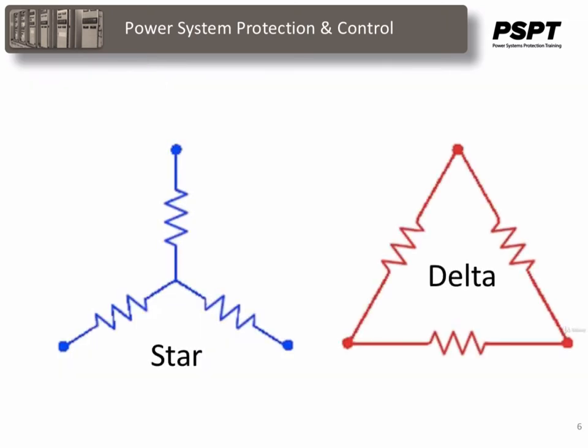The connections of three-phase circuits may be divided into two classes, star and delta. The star connection has a neutral point at the junction of the three phases, and single-phase loads may be fed from any one of the phases to neutral. Such a connection is used at some transformer stations to supply three-phase power for motors and single-phase for lighting. Delta circuits are mostly used for straight transformation of three-phase power of medium voltage range where single-phase loads do not have to be provided for.